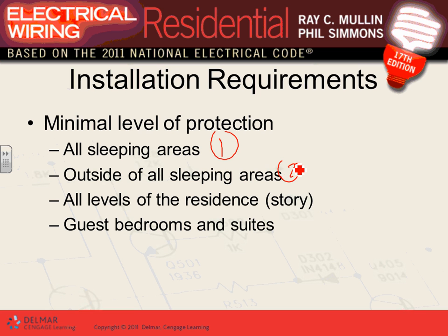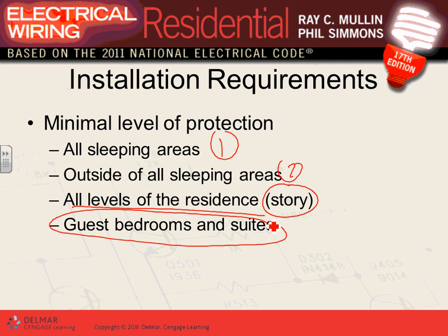Yesterday, guys, when I was walking you through, why do you think I told you this? This is coming from 72. Outside this, all levels, every level must have at least one smoke detector, regardless if there's a bedroom in it or not. So the basement, for example, where you don't have bedrooms, must have one. Guest rooms and suites, like hotels and motels, guys, they require them, the same thing. And living rooms and hallways. Any comments, any questions? Now you know where to put your smoke detectors.